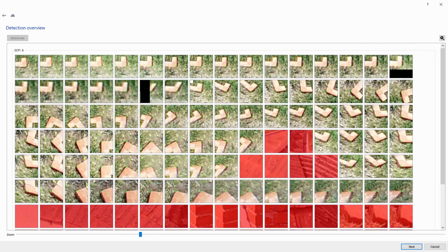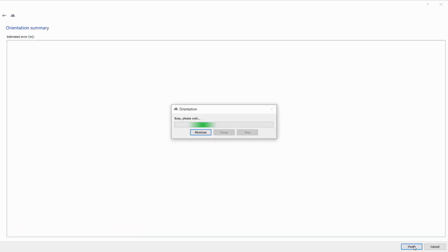I have more than a lot of good connections here, nice images which are nicely centered in the GCP wizard. And when I go to the next step, I should get the accuracy. It will be super accurate because we have RTK images with 1 or 2 centimeter accuracy. We have one GCP point which will help us to improve the height of the model, so that everything will be super accurate. We also have a GeoTIFF model in this case. And based on all this data, phone images with no telemetry will also be combined additionally, and the whole complete model will be accurately orientated.